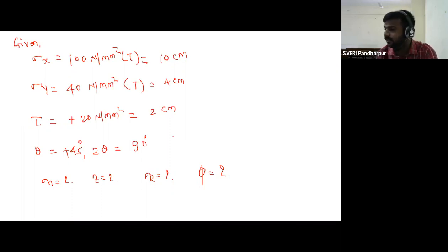If shear stress rotates in anti-clockwise direction to major principal plane, represent it in negative region and vice versa. Meaning, if the shear stress on the major principal plane is anti-clockwise, we consider it negative here, and if it rotates clockwise to the major principal plane, then it is positive.